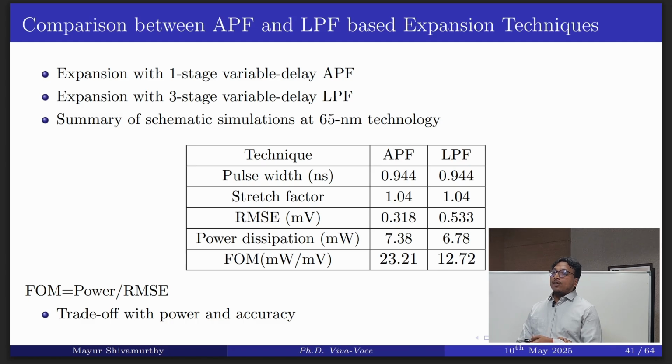In order to have a quantitative analysis between these expansion stages, which are done with the APF and LPF, we have taken a scenario where an input pulse of 0.44 nanosecond was applied as a test input for the expansion. The expansion is realized with the all pass filter and with the low pass filter, and we obtain the same stretch factor of 1.04. The all pass expansion circuit was designed with a one stage variable delay all pass filter, and the expansion circuit was designed with a 3 stage variable delay low pass filter.